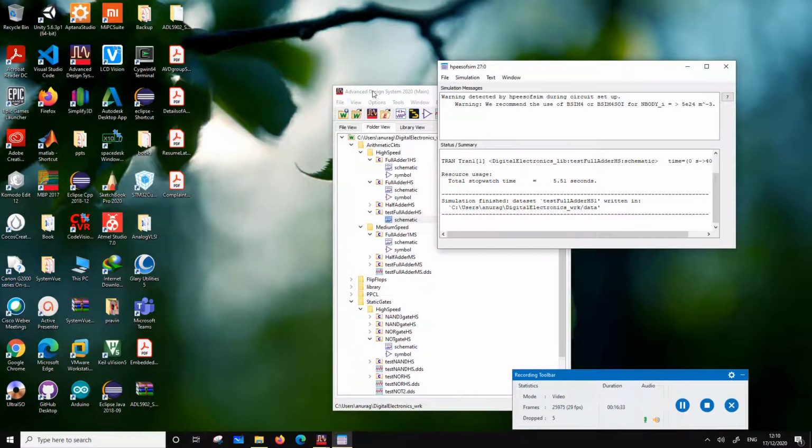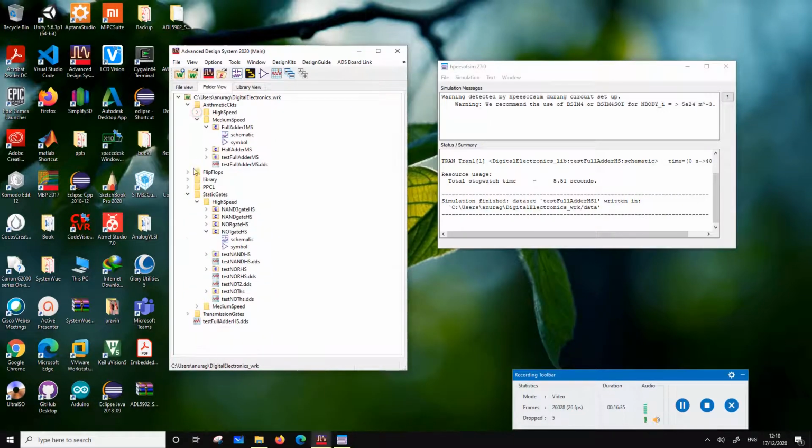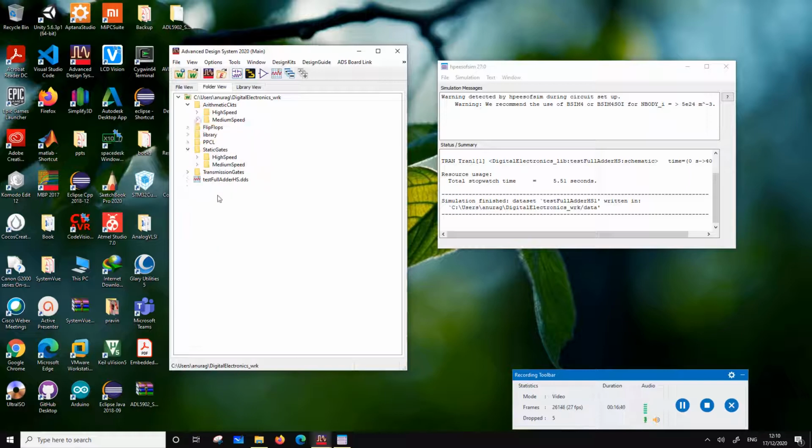Okay, so now I want to do one more standard cell, and that cell is going to be a mux gated D flip-flop, and that mux gated D flip-flop I'm going to use in a parallel to serial conversion, right? So mux gated D flip-flop, so I'm going to take a D flip-flop and just alter the D flip-flop with a mux gate, right?